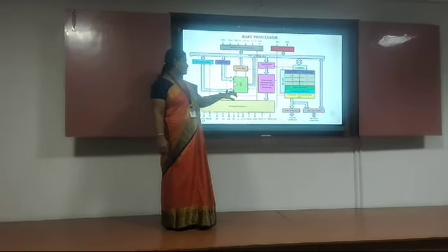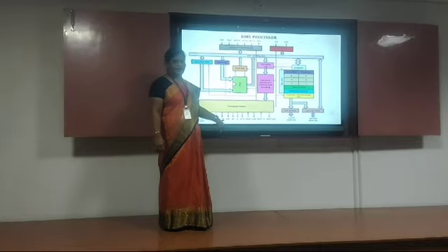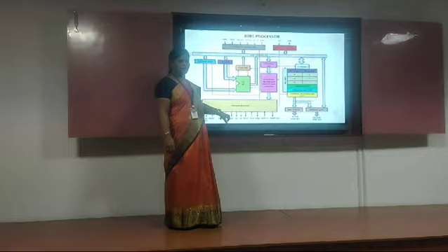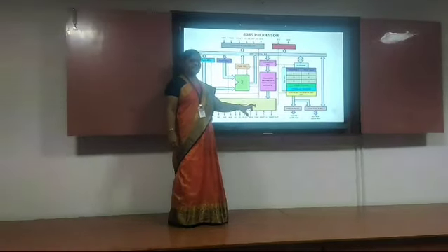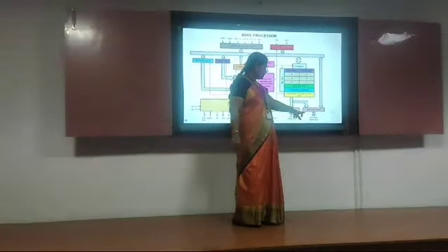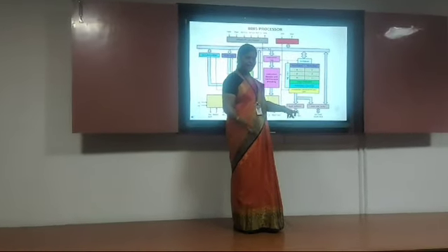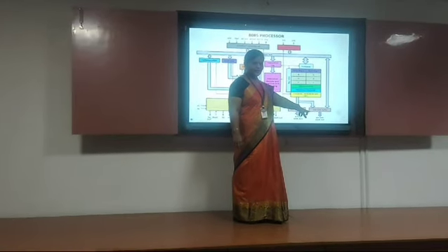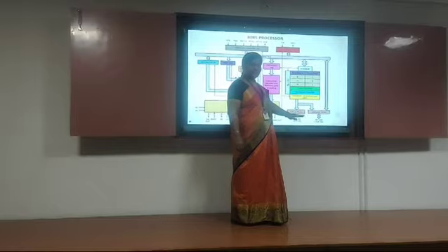ALE is different from ALU. ALE is address latch enable. So what is the purpose of address latch enable? It will demultiplex the address and data. If you see here, the lines AD0 to AD7 carry both address and data together. And A8 to A15 are separate address lines.